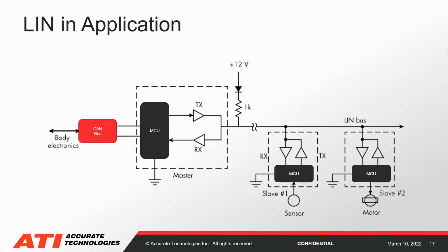Here again is another closer representation of the master, which in this case would be a LIN stalk for turning on and off the windshield wipers and turn signals, where the master broadcasts out on a single bus to each individual sensor and motor and waits for a response.